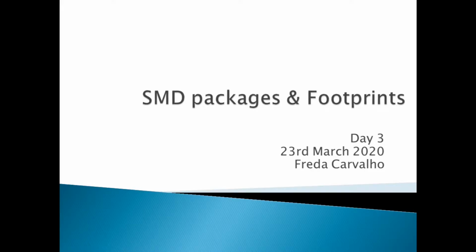Day 3 has to offer you content on SMD Packages and Footprints, followed by PCB Basics and Design Rules. You have already completed the electrical rules check on EESchema, and we have moved on ahead to the netlist generation. The netlist has to be now uploaded on the PCB tool of KiCad. So before we do that, let us understand some concepts about SMD packages.